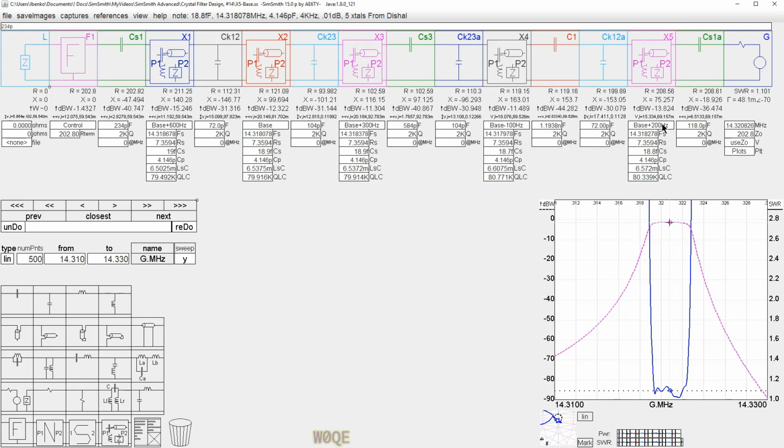And these crystals, if you were to look at these based on something you had, so you scanned them all and you made a table, you would not have picked these crystals. Let me say, I would not have picked these crystals some time ago. I've learned over time that the frequency is easy to correct. The other internal parameters are not as easy to correct.